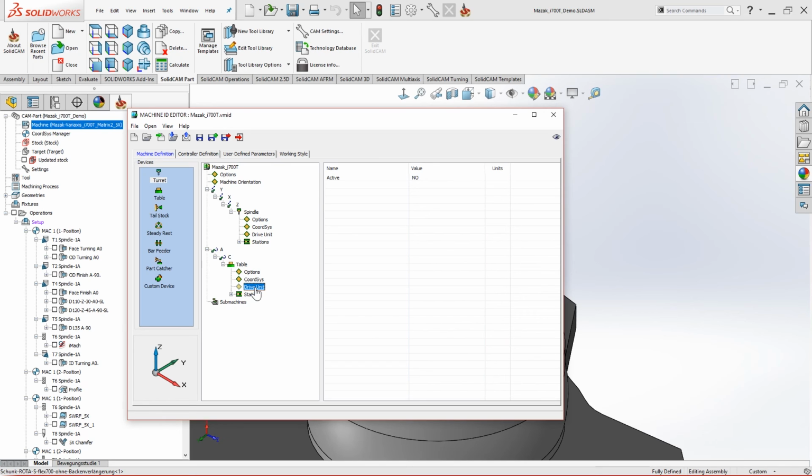That's, our table can have turnings. So in this particular case, this is a very important option. And over here we have the same parameters like the number of gears, the gear itself. I'll just set it to 1, but usually some machines, very high-end, have at least 2 gears. Very useful to use later in the post-processor.